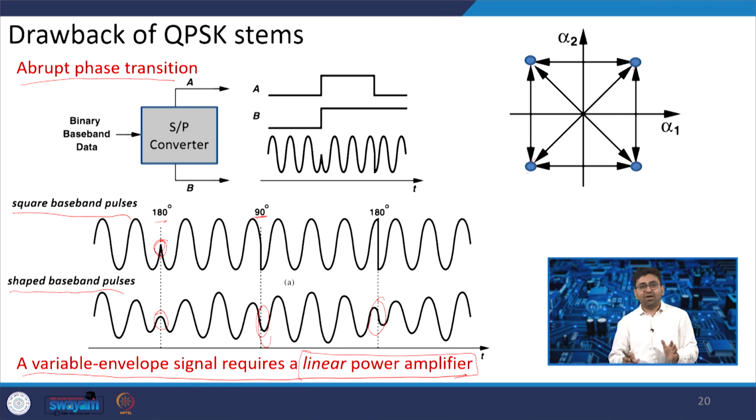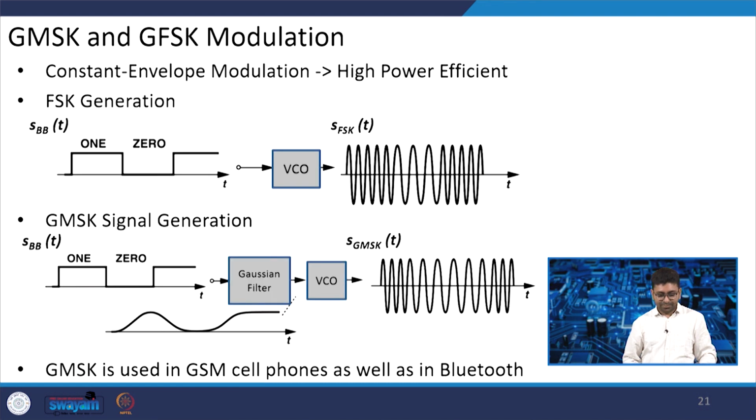So there is a trade off here between the modulation scheme that we use and the requirement of linearity in the power amplifier. This trade off should be overcome by the power amplifier designer, and on the other side the baseband engineer will try to analyze a better modulation scheme to overcome this issue. So this is a drawback that we should keep in mind.